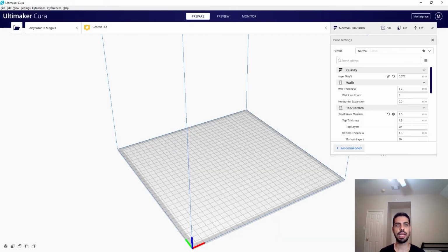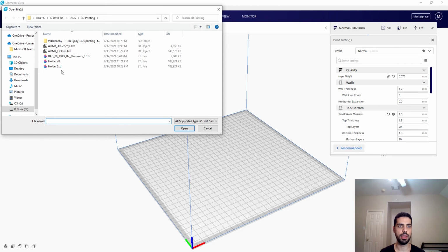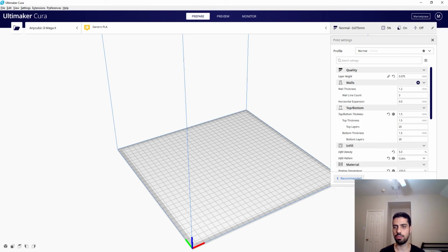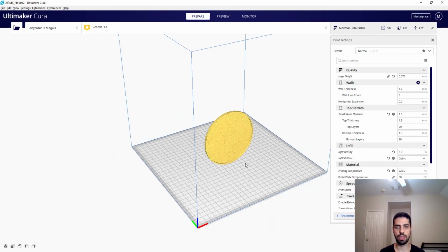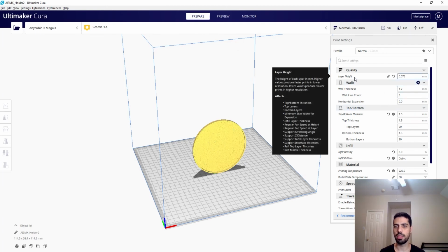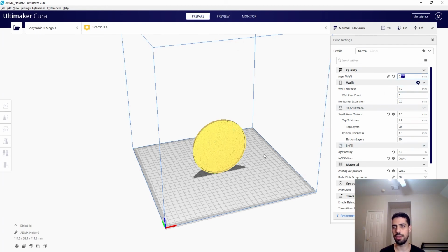And you wait. And for my slicer, I use Cura. You can use whatever you want. I'm going to open the STL, and it's going to import it. And my settings are just the regular ones. And here's the STL. My layer height, that's for a new print that I did, so I'm just going to increase it to 0.2 millimeters.